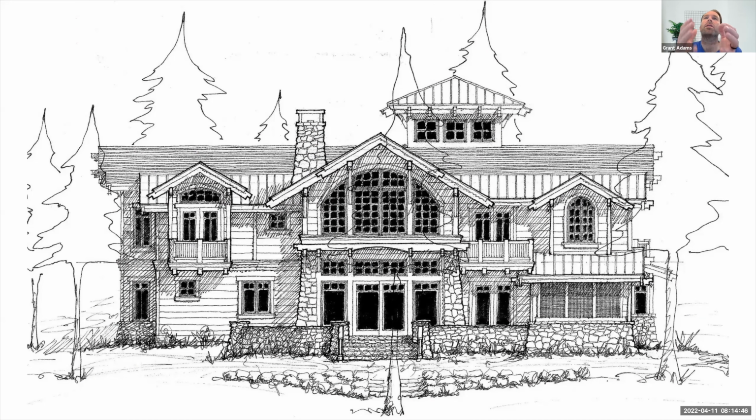So this is a much more formal elevation view. But in the same context here, we can read the depth of the building. The thickest, boldest lines are the ones right in front. So if we look at what goes up and around the sides there of this object in front, that means that this is actually the closest to us. And as we go back toward the building, the lines get a little bit lighter. So the next level might be these little pieces here on either side, then the building itself, and then ultimately this.